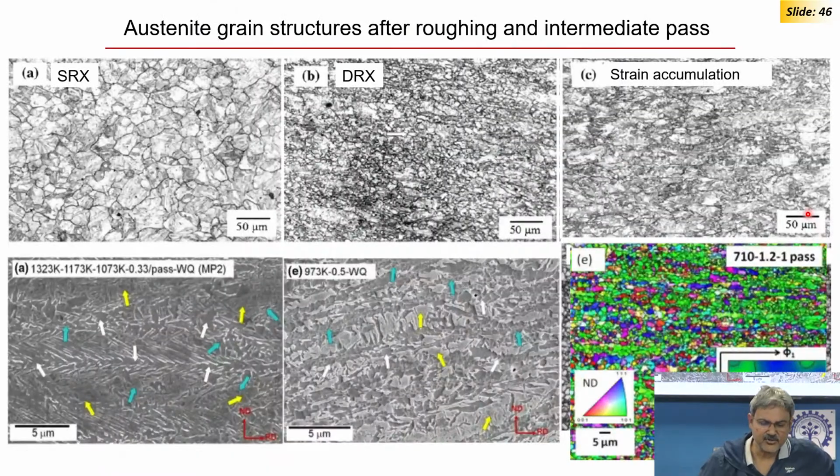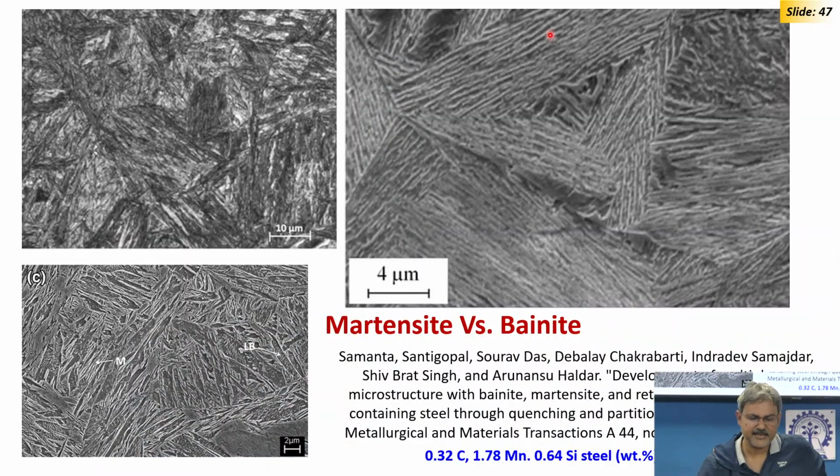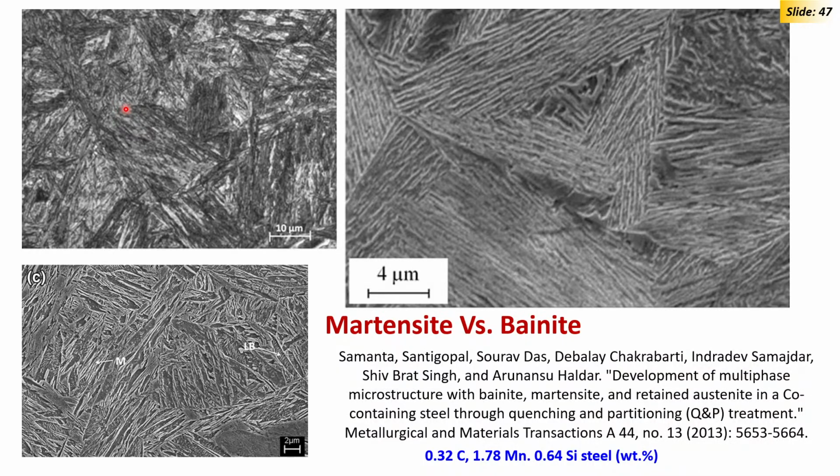If I have not shown you microstructure, so these are the martensite plates, long plates. You will find martensite plates running long from one interface to the other interface, and then other plates nucleate at the edges and grow to the interface. There can be something called autocatalytic nucleation, where a variant forms a strain inside the adjacent austenite, and the strain helps in nucleating another variant in front.